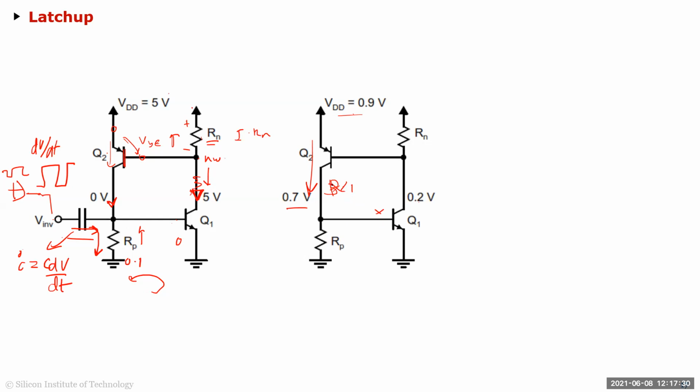That's one way. But again, I don't have that in control, because when the MOSes are made, you need a certain channel doping for VT, you need certain doping for the PN and all that, right? So those are really decided by the MOS transistors. Now, what about increasing the doping concentration? Yes, you can change the doping concentration, but like I said, the doping concentration really is decided by the MOS transistors.